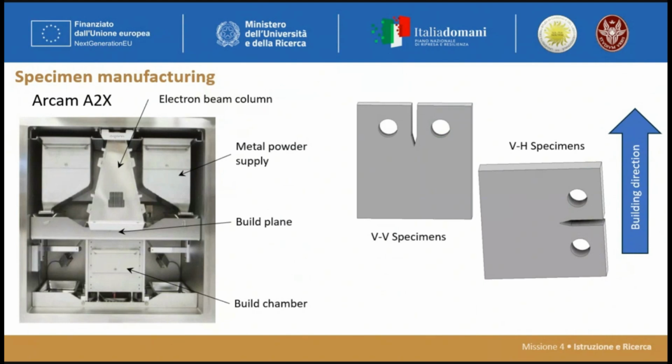After the production of the plates, they were machined to produce the notch necessary for generating the crack, and the holes to connect the specimen to the machine. It was important to note that the plates were built with the main dimension parallel to the build direction.